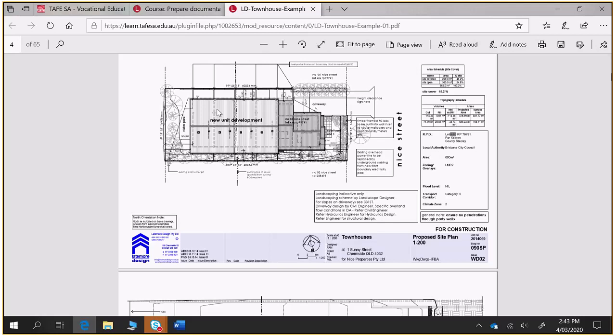Because typically you'll produce another roof plan, and you'll do that at 1:100. Your site plan is 1:200, and because you put so much information on your site plan, think about where you can have information expressed elsewhere. So I wouldn't put roof information on my site plan. But beyond that, I would have dimensions that are required.